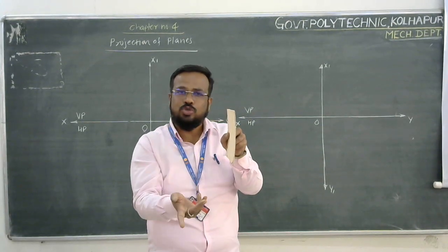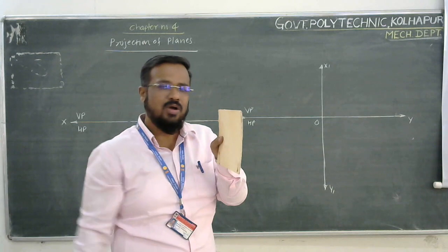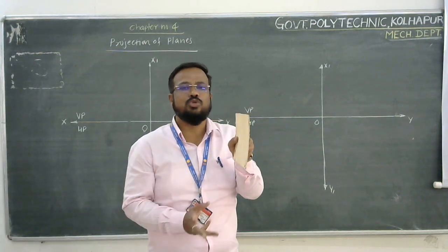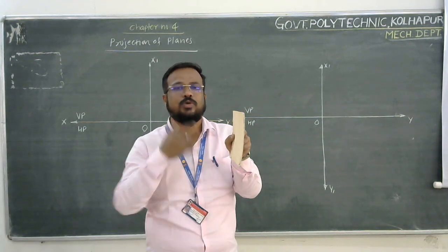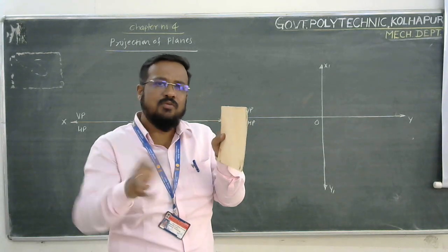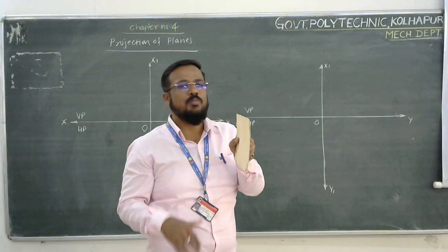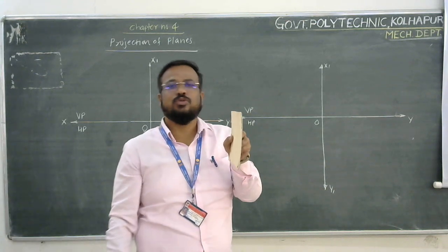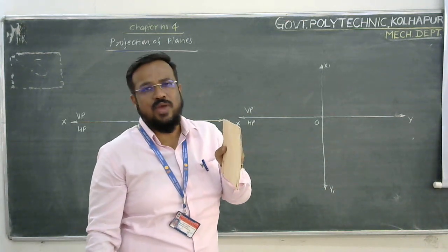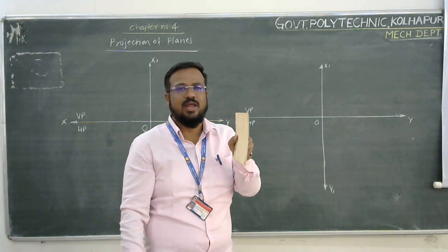Top view also shows you the exact 60 mm length of the longer edge, and no doubt the side view shows you the true shape. So you can proceed by drawing any one of the views. Either you proceed with front, or top, or the better way, you can proceed with the side view. So this is the way in which this projection of plane can be studied.